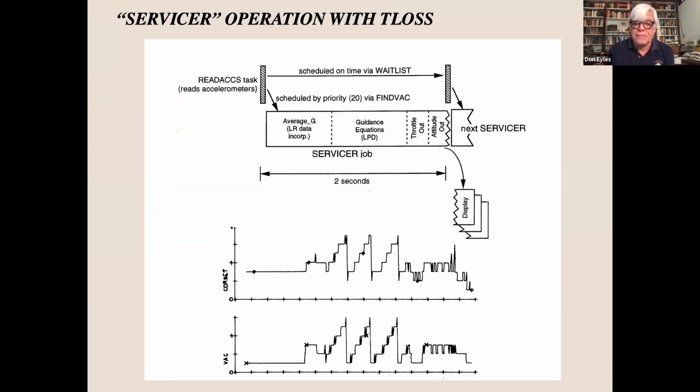And we restarted processing at the last recorded waypoint. What was happening was that the displays were being cut off by the fact that there wasn't enough time and Servicer was not finishing. Fortunately, we kept flying because the cutoff apparently always occurred after the throttle and attitude commands were issued. But there were funny things going on with the displays. During the visibility phase, it went away for about 10 seconds. During the briefing, Armstrong laughed about it, said he didn't think it was ever coming back.